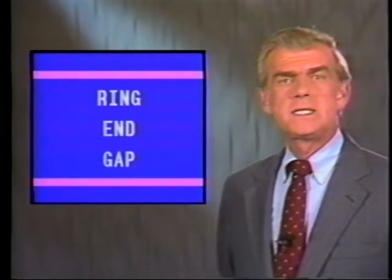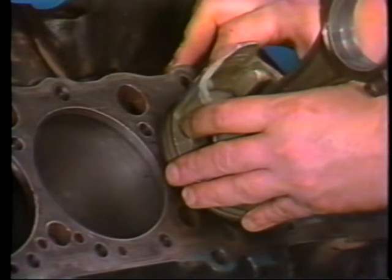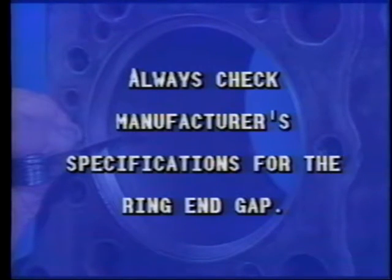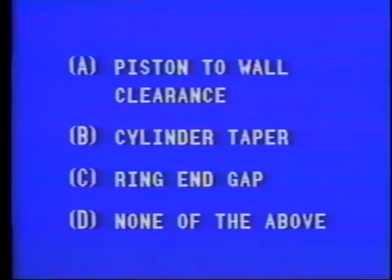When piston rings are replaced, each ring must be checked for ring end gap. After placing the ring in the cylinder, square it up by positioning it with an inverted piston. Measure the ring end gap with feeler gauges. Always check the manufacturer's specification for the ring end gap, but a rule of thumb specification is 3 to 4 thousandths of an inch clearance for each inch of cylinder diameter. If the gap is too large, oversized rings may be required. If the gap is too small, file the ends of the ring until the proper clearance is established. Looking at these procedures, you can see that the correct answer is response C, ring end gap.